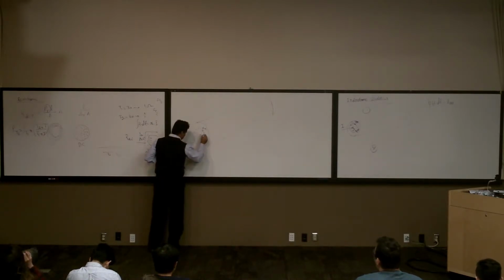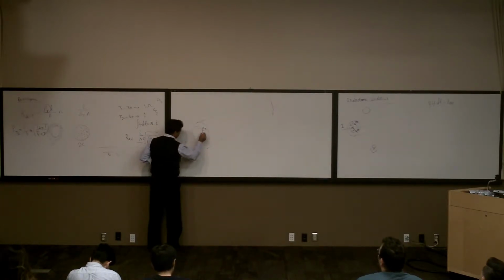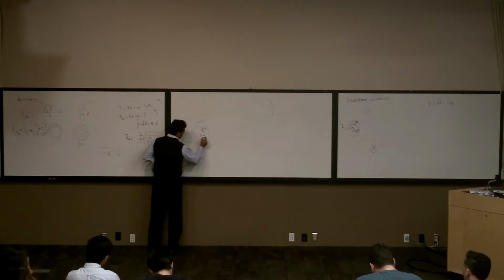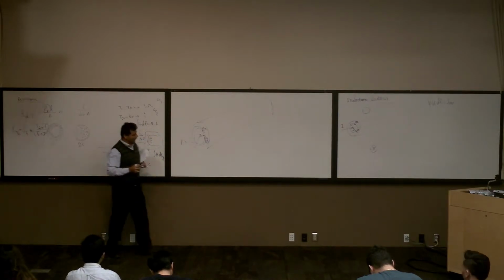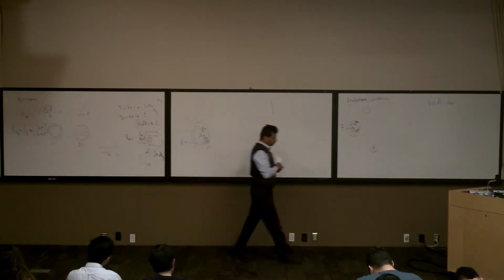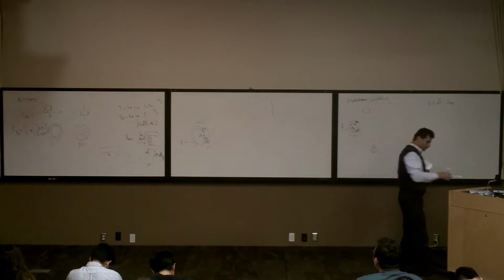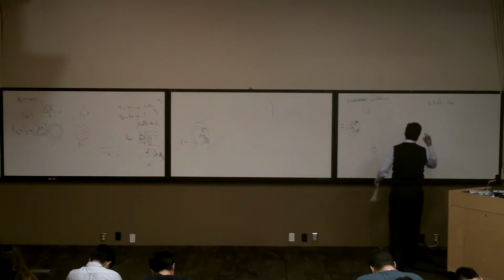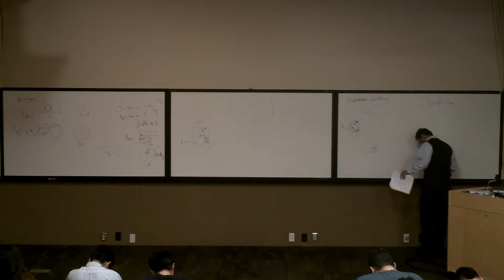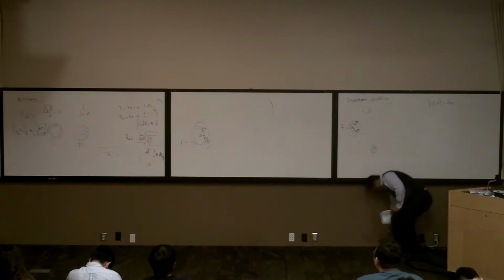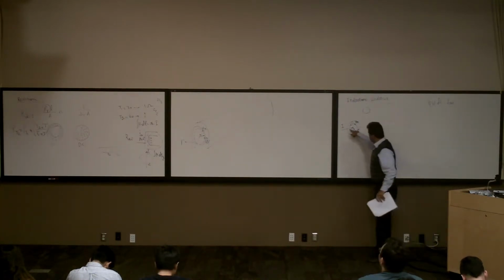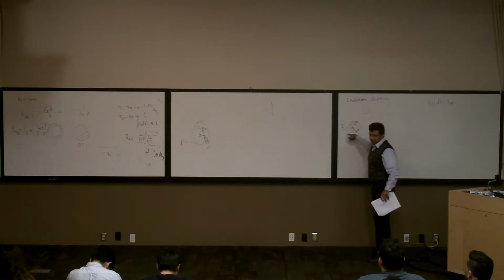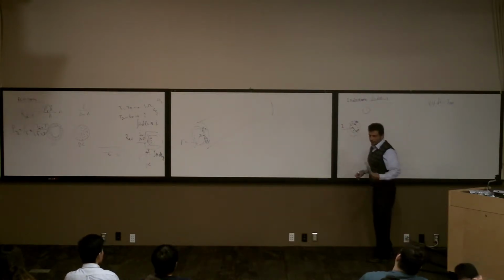Let's assume there is a little bit of increase here, and I'm going to write it big: dx. This is dx and this is x, right? Let's go through the integral. We say the integral of H dl is equal to I net. On this circle, H is fixed, so it can come out of the integral.